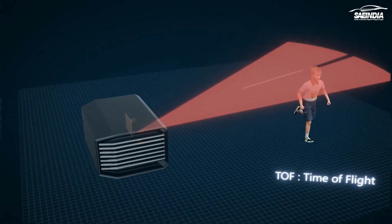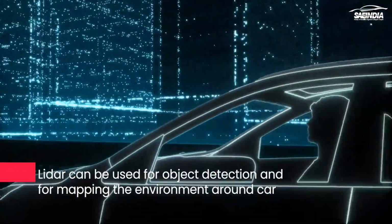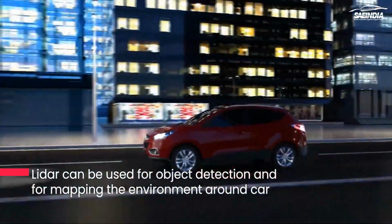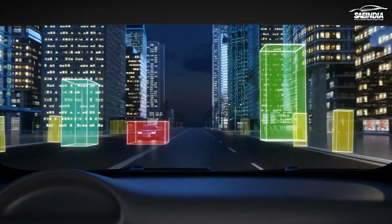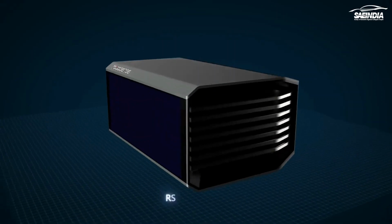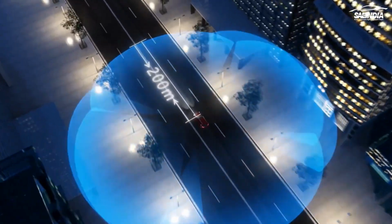LiDAR captures a high-resolution point cloud of the environment. They can be used for object detection as well as mapping an environment. It uses the same principle as the time-of-flight sensor, but at much longer distances: a minimum of 75 meters for near field and 150 to 200 meters for far field.